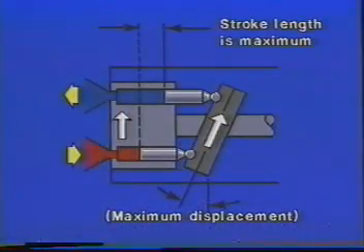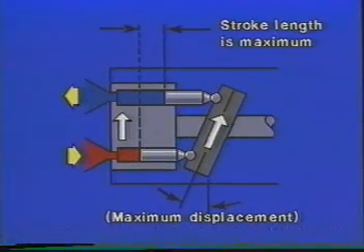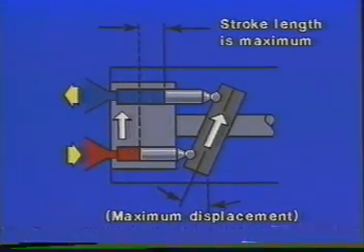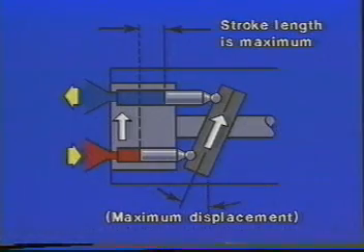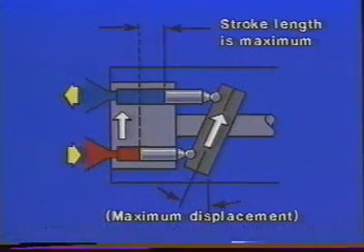Because of their construction, piston-type motors will usually allow us to operate at higher pressures and speeds than comparable vane or gear units. Here's a simple view of the inside of an inline piston motor. Oil directed into this port gives a force in this direction. Part of that resultant force produces a torque for rotation. The angle of displacement determines the stroke of the pistons and the torque and speed capabilities.